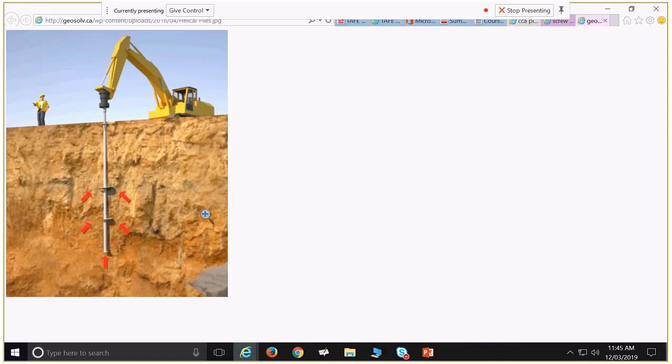Wow. So in South Australia, we don't do any screw piles anywhere near that sort of 38. No, we're not dealing with that sort of thing. In fact, even that is relatively crazy. Well, ours would be about 5-6 meters deep. But a screw pile is just a steel tube with some angled pieces on it, just like an auger, that screws down into the ground. And of course, by screwing down into the ground like that, it locks into the ground really well.